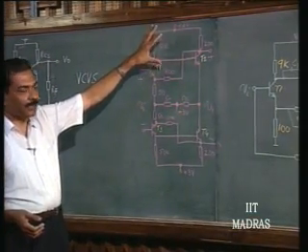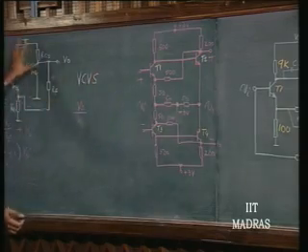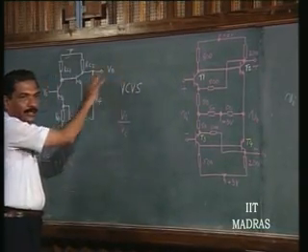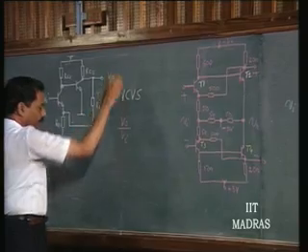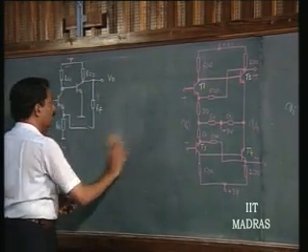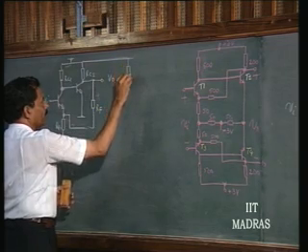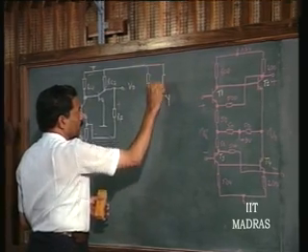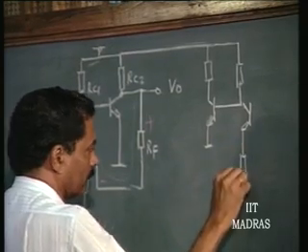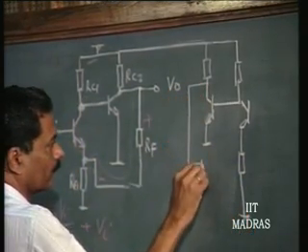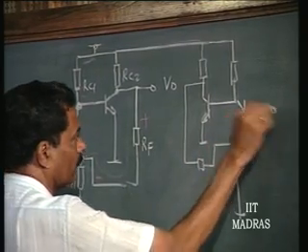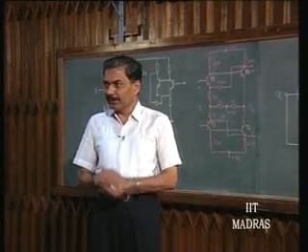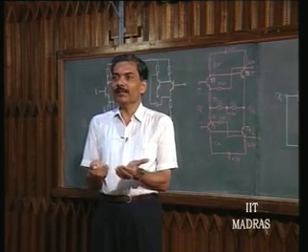You can see this is one of the commercial integrated circuits fabricated using this kind of H feedback. I have just merely repeated an exactly identical stage here. You can do the same kind of analysis that we did while converting a differential configuration. Just simply repeat the configuration here, then convert every one of them into what? Differential mode by introducing current sources or common emitter resistors.